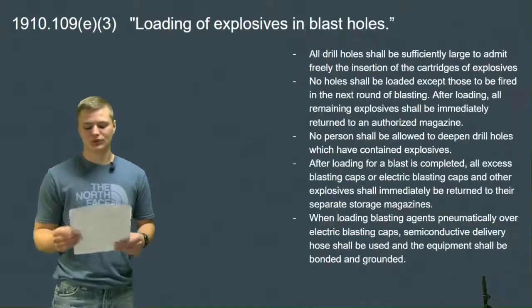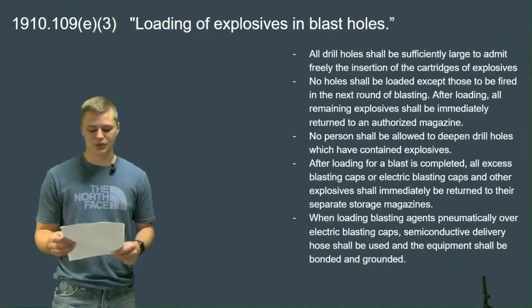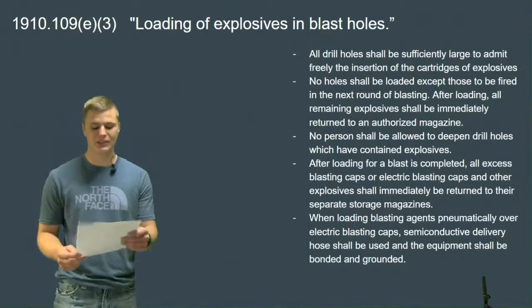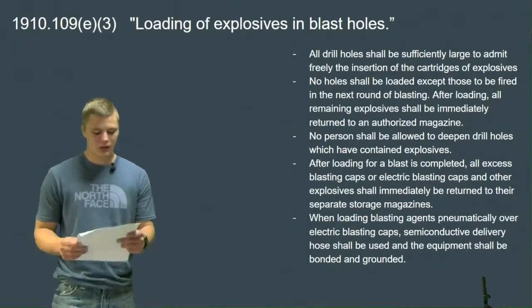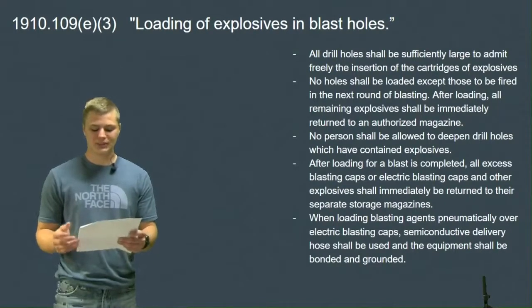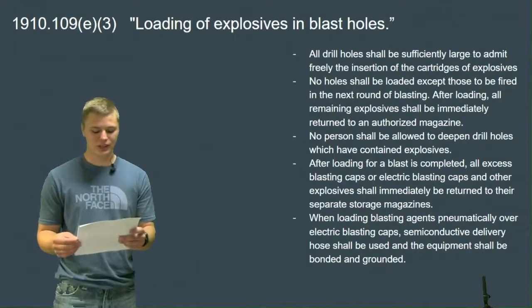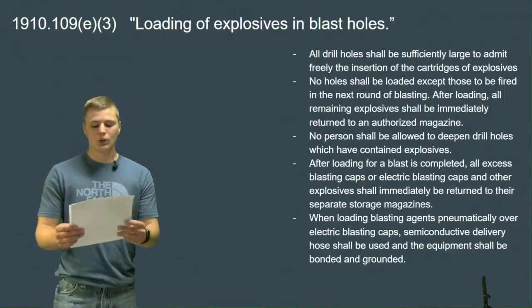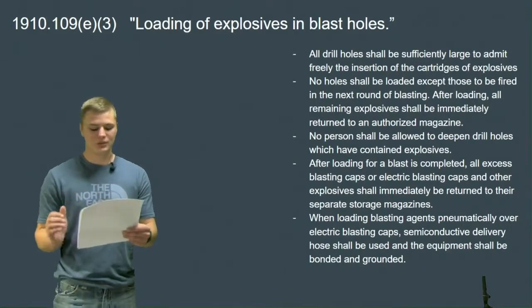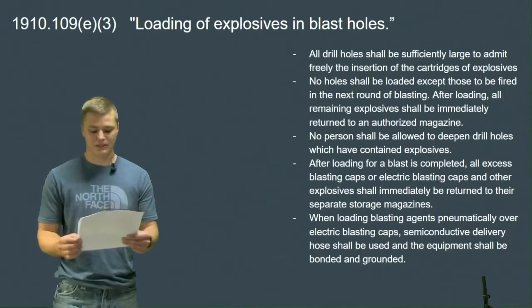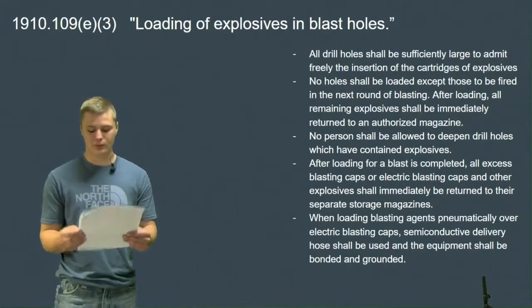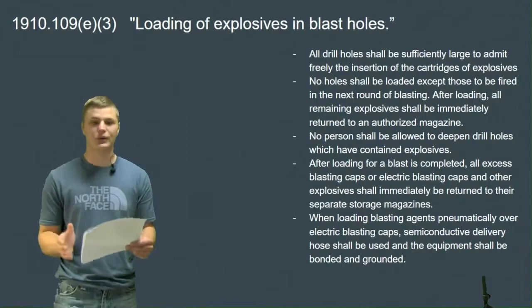Now that you know the rules of storing the materials, we are going to look at how to be safe when handling and loading explosives in blasting holes. All drill holes shall be sufficiently large to admit freely the insertion of the cartridges of explosives. No holes shall be loaded except those to be fired in the next round of blasting. After loading, all remaining explosives shall be immediately returned to an authorized magazine.